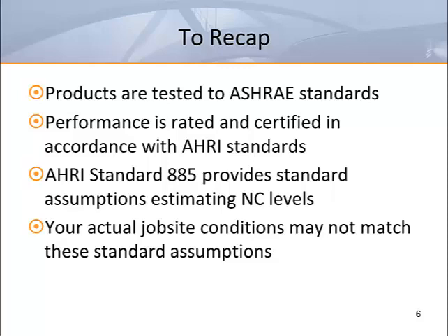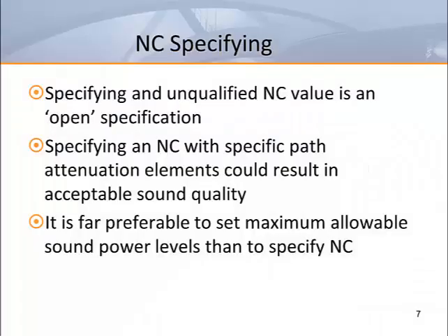So now let's move on to some new topics. Many project specifications that I review include scheduled maximum allowable NC levels for various products without any information regarding the sound paths. Now it's impossible to know whether a product can meet such a requirement with so little information provided.